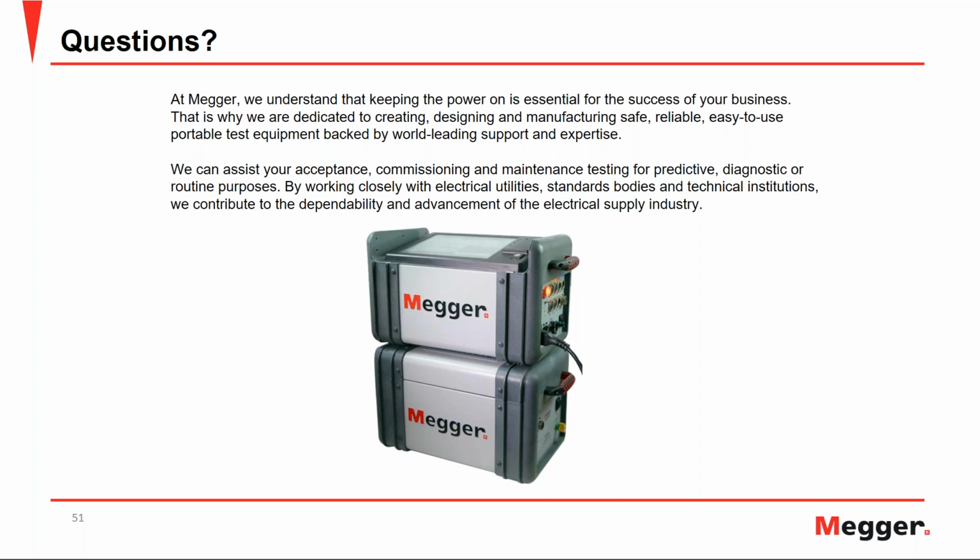And typically, if the capacitance value changes more than 5%, that is an indication that something needs to be further looked at. And one test that you would perform would be the SFRA test, because we are talking about mechanical changes.